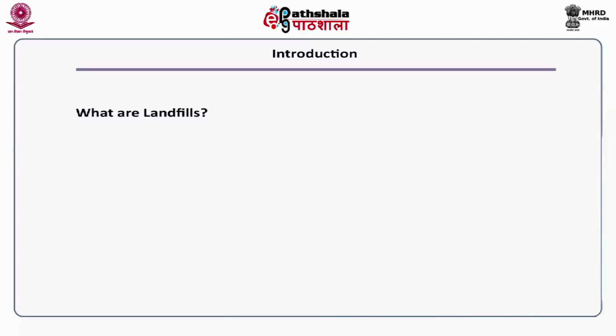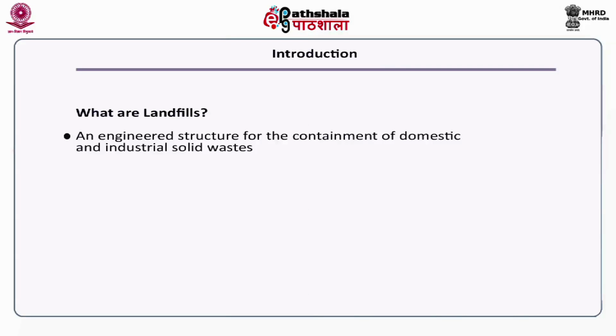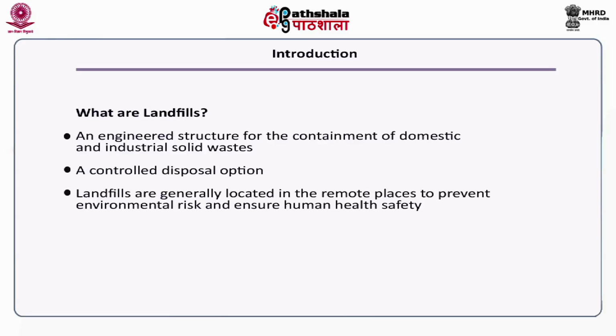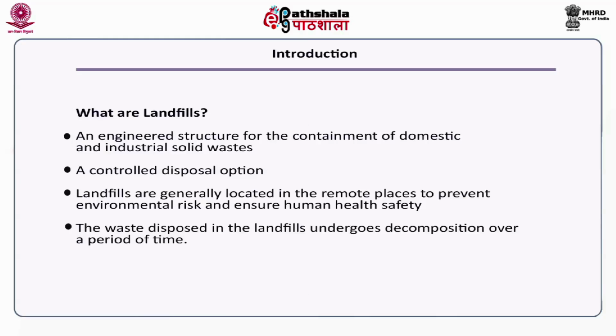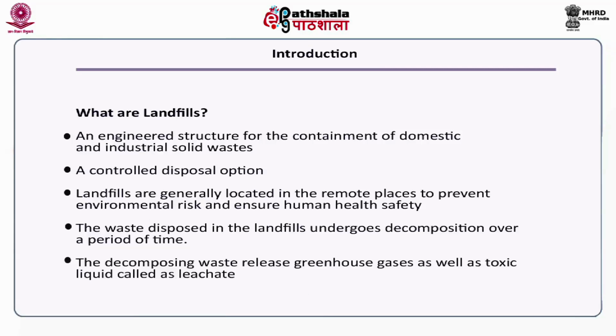First, we will start with what a landfill is. A landfill is an engineered structure for the containment of domestic and industrial solid waste. It is one of the controlled disposal options. Landfills are located in remote areas, mainly on the outskirts of the city, to prevent environmental risks and ensure human safety. The waste disposed in landfills undergoes decomposition over a period of time and releases various gases and a toxic liquid called leachate. The gases are mainly greenhouse gases like methane, carbon dioxide, NOx, etc.